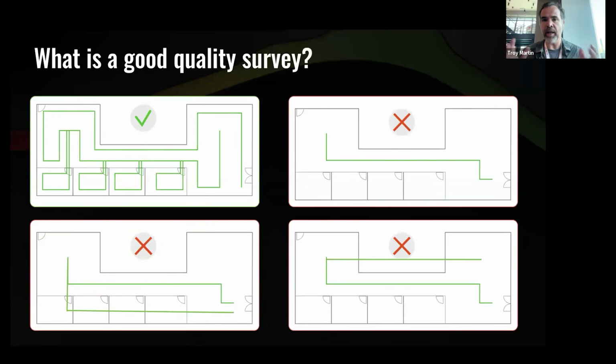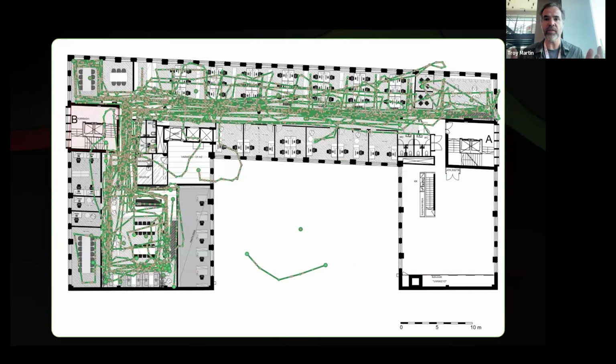And most people, I haven't seen it yet, aren't equipped with rocket packs or jet packs to survey. So if you're surveying the fourth floor of a building, there's a good chance that you're not flying outside the building, cutting across from one section to the other, right? So if you're not literally using a jetpack to hop between decks, you don't want to click and mark a survey path as if you were walking outside of the wall of your building. Right. And these are common examples of things where it's immediately obvious that someone's clicked wrong or made a mistake while surveying.